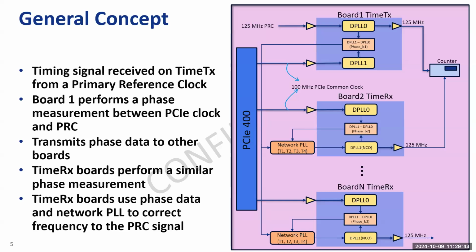Which effectively is why PTM has some limitations, right? I know there's been a lot of discussions on PTM, and it's always been highlighted that although its concept is good, one of its limitations is if you have two free running clocks on both sides, there can be tens of nanoseconds of error over time, a variation between those two clocks, right? So that is no different in this situation. But as you highlighted, because we're trying to focus primarily on frequency, it may not be a huge impact, but it just needs to be studied and looked at.